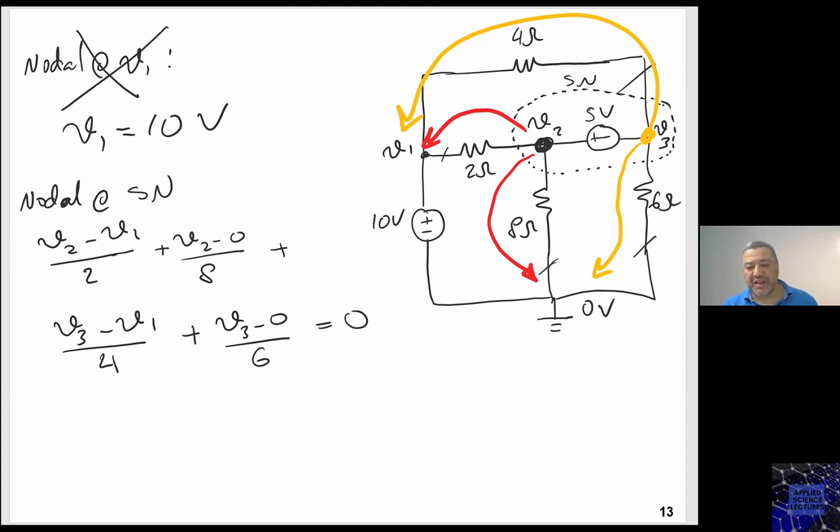Now, the second supporting equation that I need not to forget, because at the end, I do have 2 variables. One equation is not going to help me. There is a second supporting equation. Where does it come from? It comes from this binding condition that we have talked about, which is V2 minus V3 equals to 5 volts.